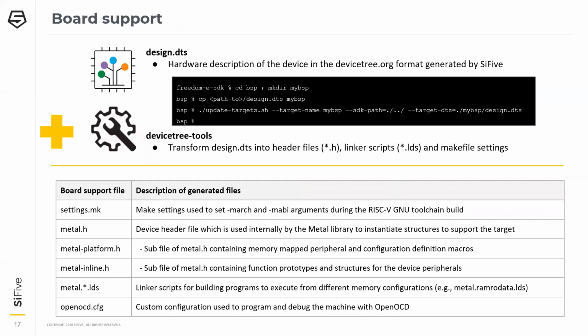There are a few linker files created as well for running from different memory locations. Some development boards have QSPI flash, and other times you might want to tune a function or algorithm running directly from RAM to get the best performance, say benchmarks, for example.